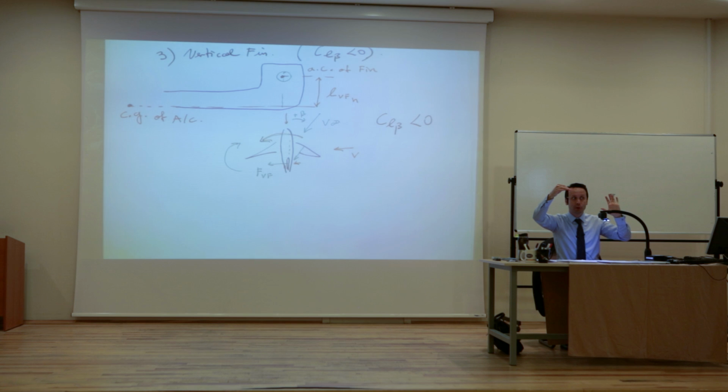And without controls, without touching the controls. Because the control for the pendulum was that force that I could just move that thing with my hand, right? So which really means that, if this is the equilibrium point, with my hand I could actually move it the way I want, right? That's not a stability characteristic. Control is just, I can control it with my hand. Stability is just, will it come back? Without touching it, will it come back to the equilibrium point?